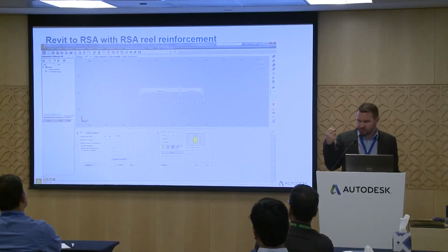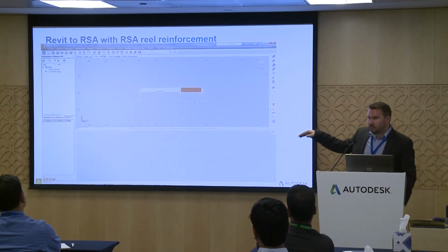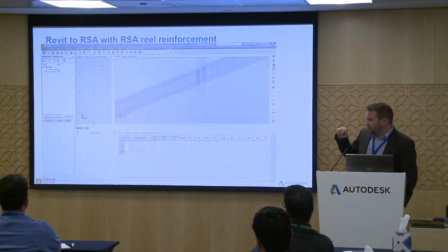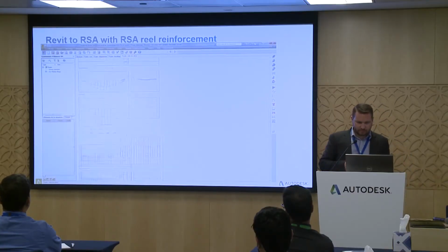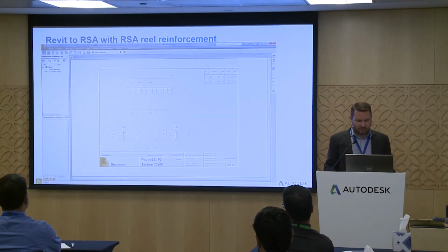Here I have the reinforcement, and here I select to go to real beam, and so it imports the beam. Here the FEM will come from the general analysis, of course. But if you have a simple beam, there is another option you will see after, where you just have to put your loads, and it will create the same. But you have to know the loads, and sometimes that can be difficult.